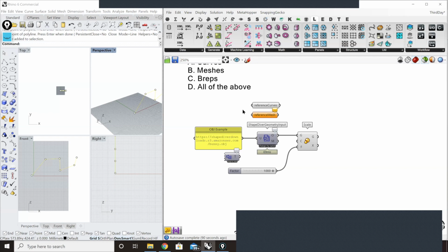So the geometry information, I mean, you can answer for both the OBJ and DXF formats. Right now, for DXF, can you get the colors? Yes, you can, but you can't get all the metadata that's included in the DXF besides the color for now. We'll extend this, especially because we'll extend to other formats, so 3DM, for example, and import more metadata about colors, attributes, and all of this. For now, it's mostly meant for pure geometry, so meshes and curves, basically.